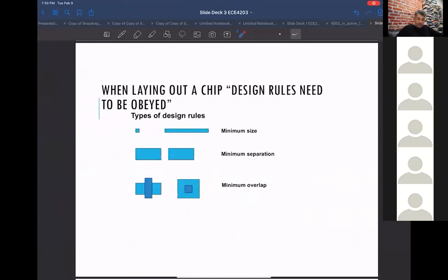Okay. So, any questions so far? I know it's a little confusing without having the computer-aided design rules to play with, but you're basically overlapping these different rectangles or squares in different layers to build up your transistor definitions and connections between the transistors. Now, the design rules are telling you, if you can imagine building these things, there's a couple of possibilities of failure.